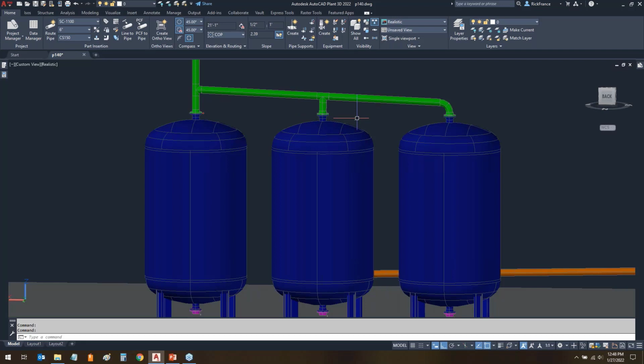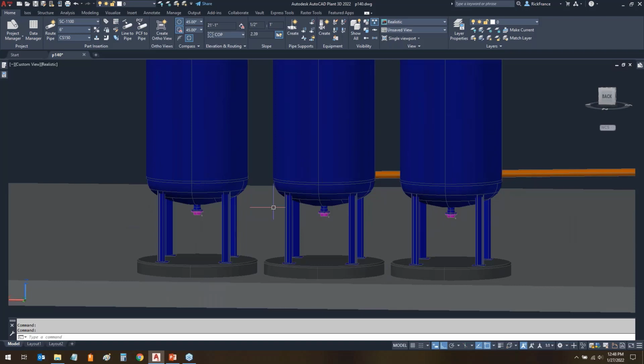Now we're going to do this once more with fitting, just to let you see it in another situation, because this one was pretty complex because of that T right there. Down at the bottom here, I'm going to be doing the same thing. I left my flanges because lots of times when you draw, you may have drawn the pipe and you're erasing it. Don't erase the flanges, then you don't have to worry about the slope tolerance connecting with the nozzle, because the slope tolerance will be considered for a flange. So in this case, I want to leave the slope 1/2 inch equals a foot.